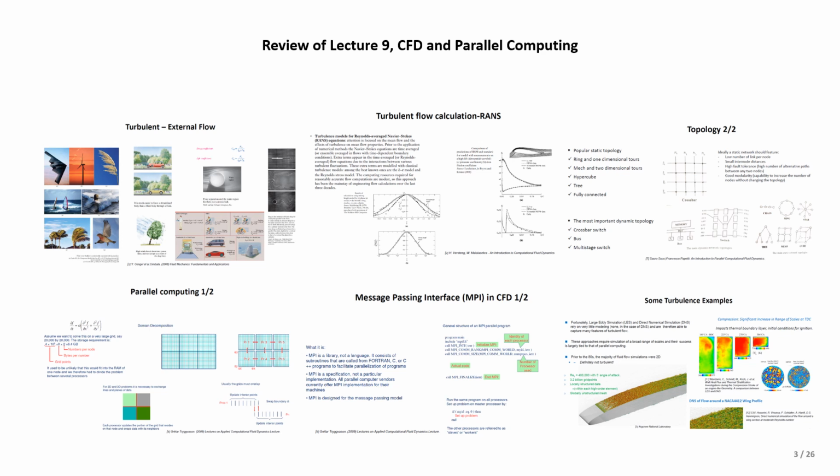When we use LES, the accuracy is higher than RANS, but it is much more expensive. Based on the literature and some studies, they made comparisons for the same CFD cases: LES is around 5 to 10 times costlier than the RANS method.